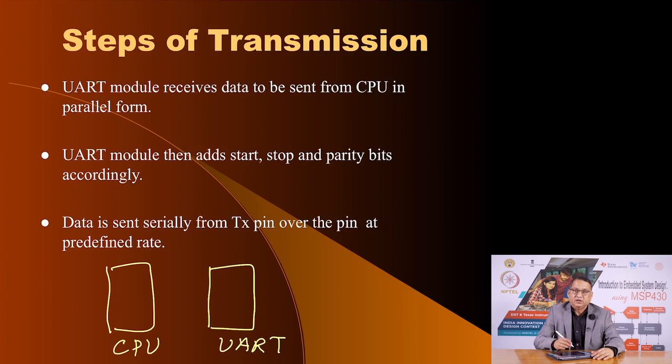Both of these building blocks are integrated in the same chip, but the CPU will transmit the data that it wants to transmit from the CPU to the UART. The UART will add the start bit, and it will serialize the received data. At the end of it, it may add a parity bit as well as a stop bit, and this data will be sent on the TX line, TXD.